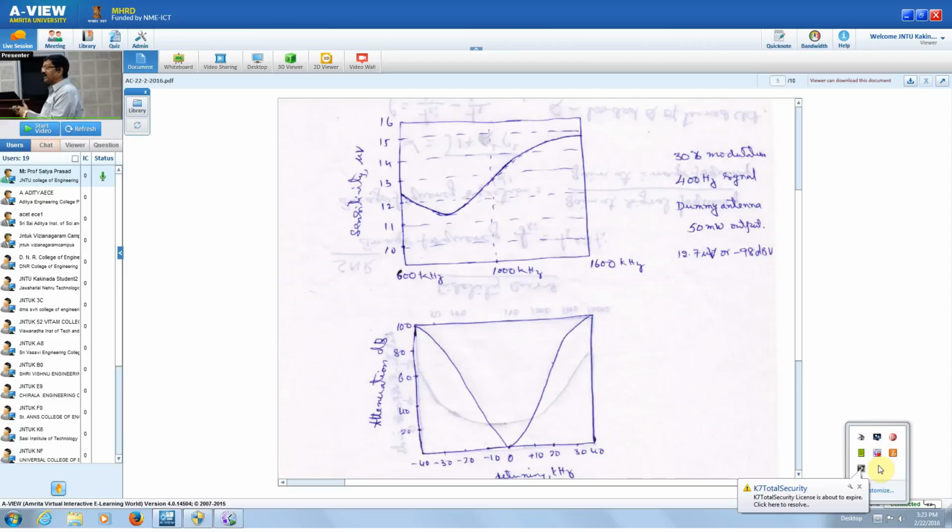Because you are having a tuned circuit, the output will be reduced. Now what we are doing is, see that 30% is maintained constant, and see that you are getting 50 milliwatts again at 805 kilohertz. Measure that value, because that value is much higher. This is the minimum value.